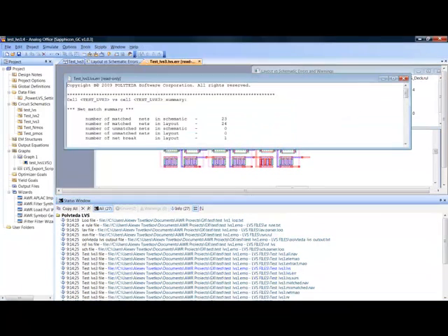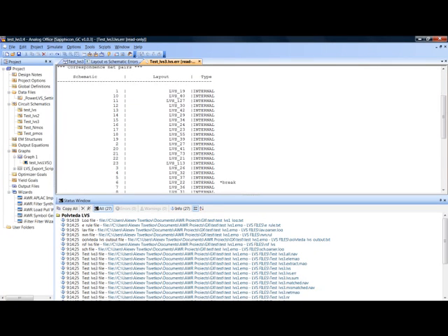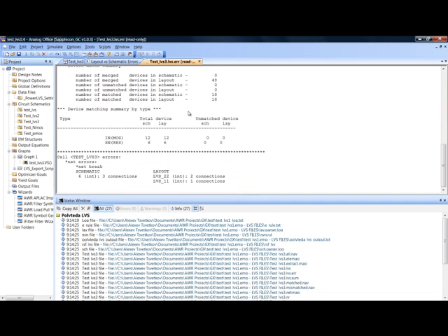And again, you can see the error browser. If we look in the error report yet again, we notice right away that there's an open reported for one of the nets in the match net pairs list. At the bottom, we see the exact net names involved in the open on the layout side, and the single schematic net that matches those nets.